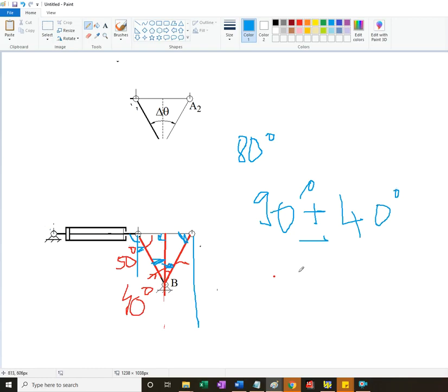So suddenly we can tell what the maximum angle of swing of this could be in order to stay within the recommended limits of the transmission angle. So if I want the transmission angle to be plus minus 45 degrees, then I cannot go more than 90 degrees angle of swing. If I go plus minus 60 degrees, this could be 120 degrees maximum angle of swing.